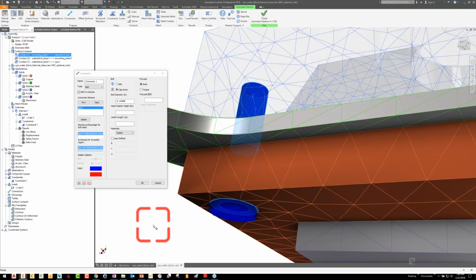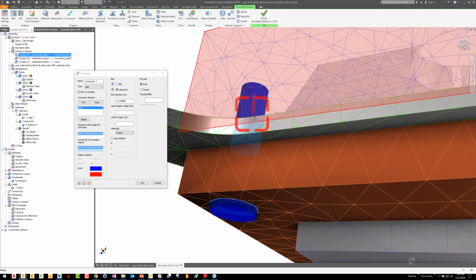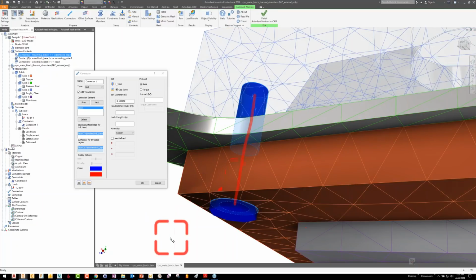It looks like a solid model of a bolt, but it's just a rudimentary glyph. It's not actually building a solid. What it's going to build is a structure that's essentially a line element going through the hole, and it's going to use the beam element type, which is a very simple way of representing structures that are long and have uniform cross sections. Much more efficient than trying to mesh a bolt in 3D, but will still give us useful information like the axial force that the fastener is undergoing as a result of the loads on the assembly.